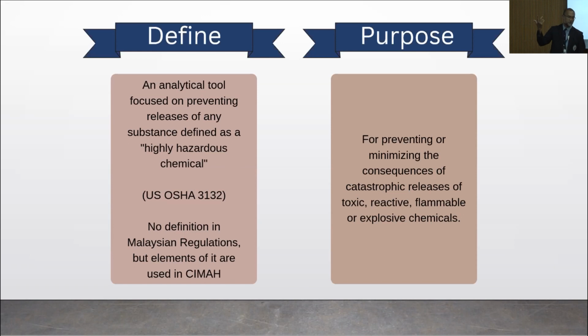The previous speaker gave you examples. For example, you have Bhopal, you have Texas City Refinery, and in the oil and gas industry, we have Piper Alpha, and then all that. Those are considered things we could fall under. So you have your definition of what PSM is and the purpose of what it's trying to do. However, you can use the principles of PSM at any level. It's whether it's worth the bang for the buck. It takes effort to implement PSM, and depending on your risk, it just might not be worth the effort.